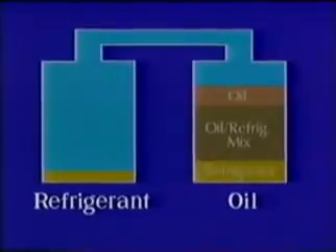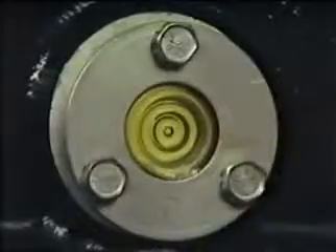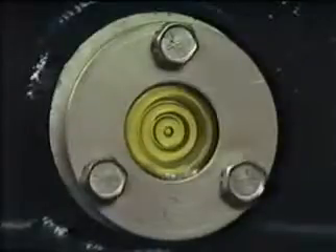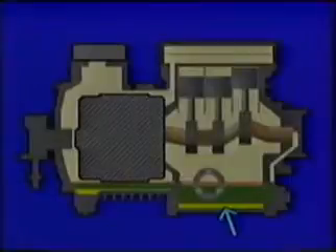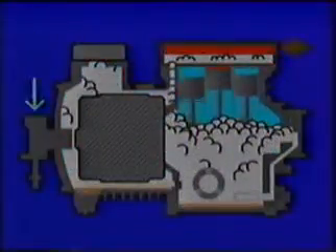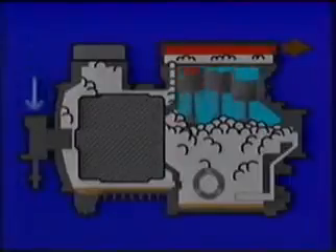If there is more refrigerant than the oil can hold, the excess refrigerant will settle to the bottom of the crankcase. A migration problem can easily be confused with high oil level, since they appear identical when looking into the sight glass. But when a refrigerant-cooled compressor starts up with this refrigerant-rich oil in the crankcase, the sudden reduction in pressure causes a violent reaction. The lower pressure causes the refrigerant in the crankcase and motor compartment to literally explode out of the oil. This explosion looks like a white foam.